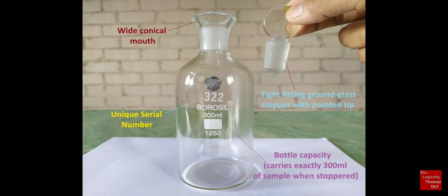The BOD bottle has a wide conical mouth and a tight-fitting ground glass stopper with a pointed lower tip. These are unique design features of the bottle to avoid the trapping of any air bubbles in collecting the water samples, and also to minimize contact between the sample inside the bottle and the atmosphere outside.